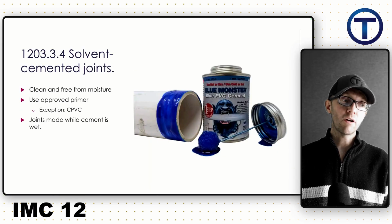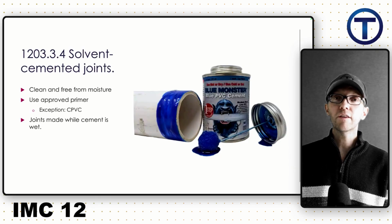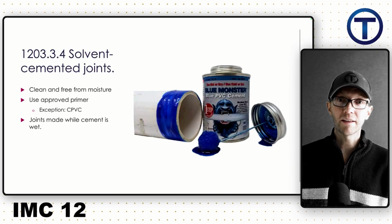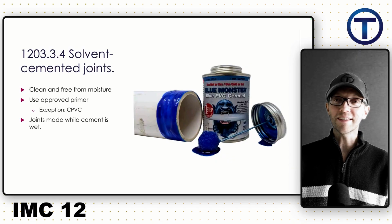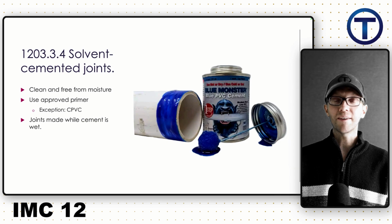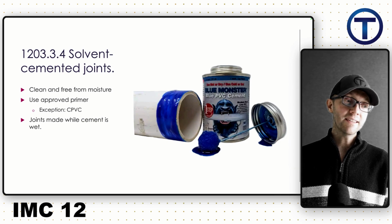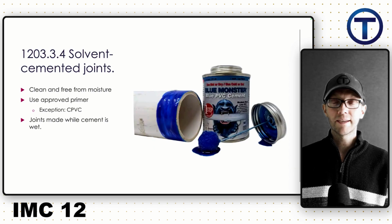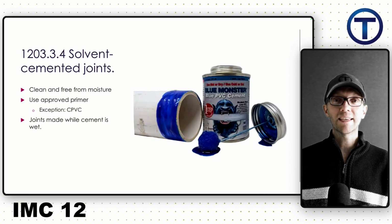1203.3.4 gives us solvent cement joints. Now, you might think that gluing pipe together is easy, and you're right, it's not that hard. But there are some things we should keep in mind when we're doing this. Keeping the pipe and fitting clean, or cleaning them beforehand, and free from moisture. So if it's raining when we're installing, that makes it difficult.